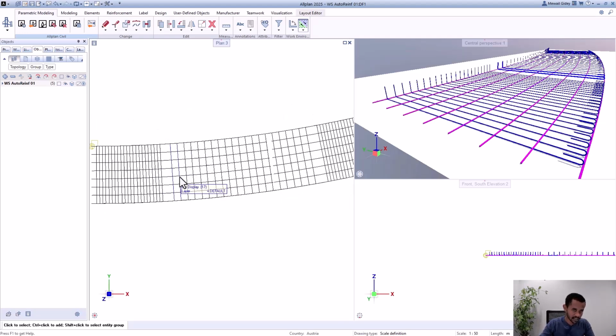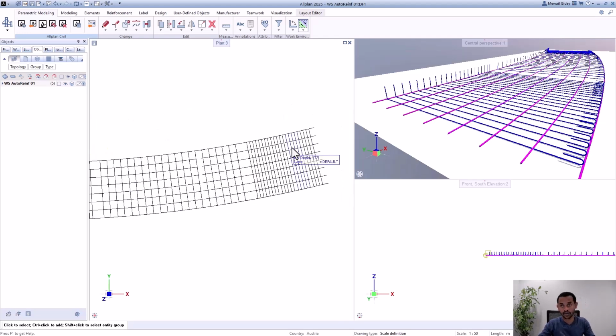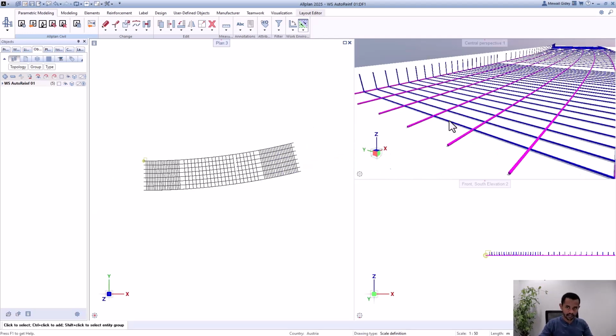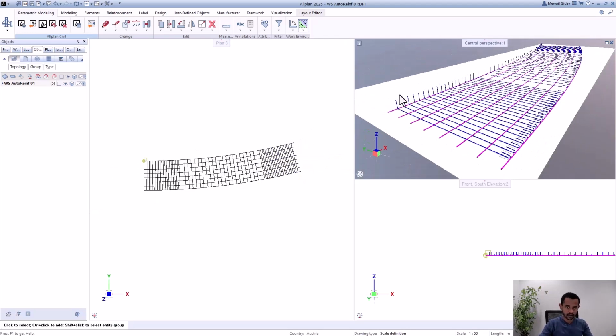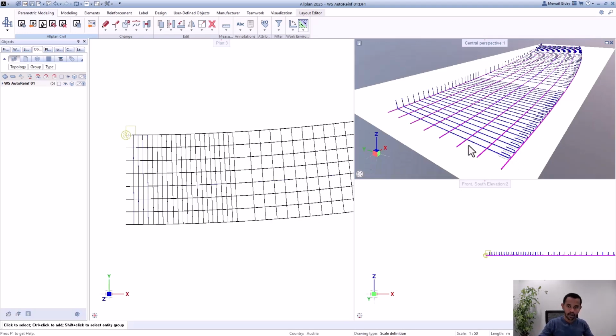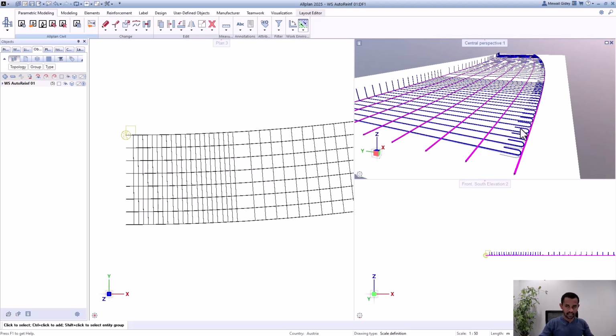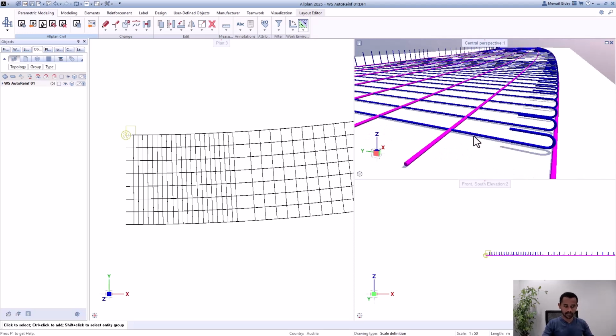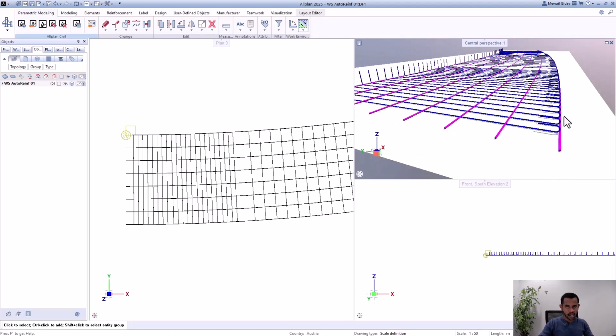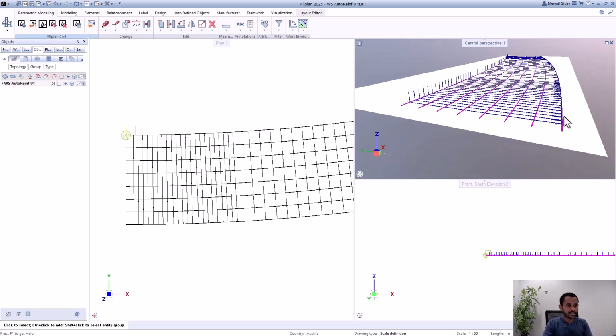Again, you can see the spacing and so on is quite different because we already set it up once and saved it. If you don't want to, you don't need to set up the spacing, you can just avoid that, or the area, avoid that, and just load only the hook lengths at the beginning and at the end. Yeah, so we have everything set up as we wanted to. The same thing as the longitudinal ones, we could also transfer back the shear and play around with the transfer of reinforcement area, which is quite great so far.